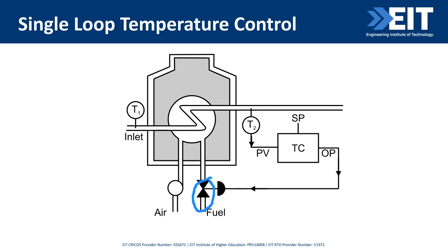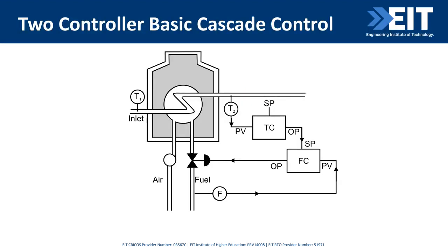So here, your inlet temperature is coming in, and here's your outlet temperature. All you're doing is, as soon as you see a change in the temperature from your target value, you adjust the valve. So you may say, look, I'm going to do some control of that valve, and I need to create a cascade loop. So this is the classical application. Can you see what we've done here?